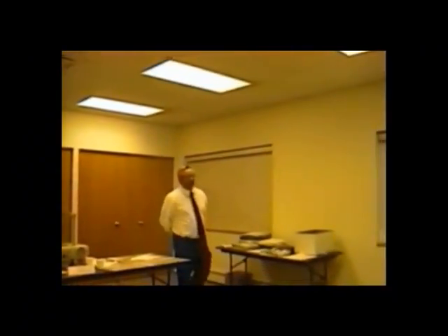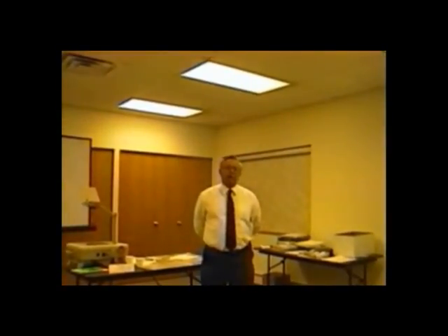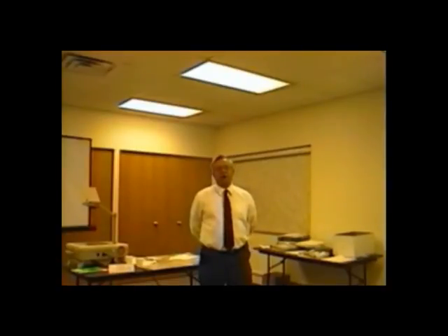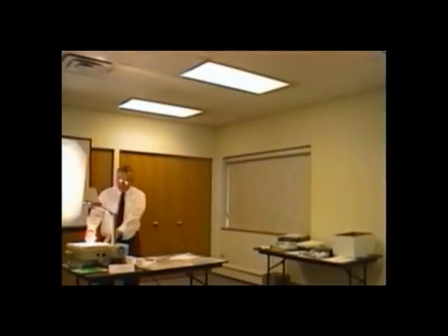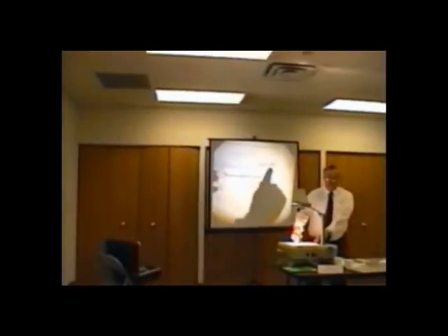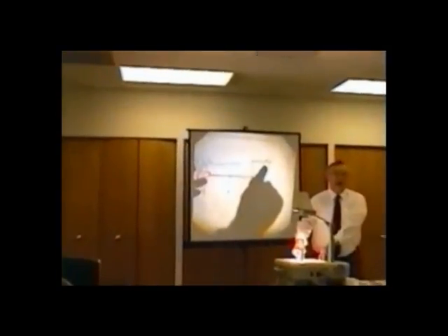Let's talk about it. The customer says, darn you and darn your air conditioner. You told me that if I purchased this new high efficiency system, it would cool the same way and my electric bill would be so much less. Well, I got to tell you, it runs forever, it never shuts off, doesn't cool the house, and my electric bill is sky high. And ladies and gentlemen, isn't that what we just did over here? Less capacity costs you a fortune in electric, runs constantly, and it cannot do the job.